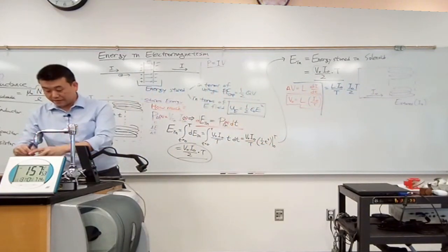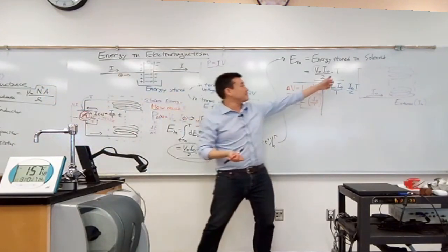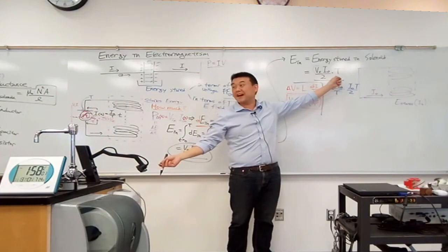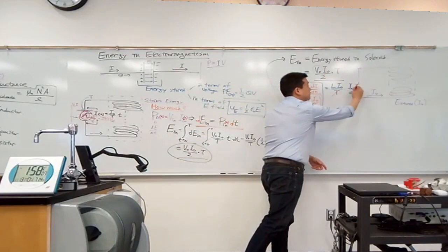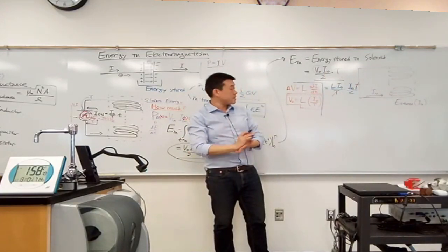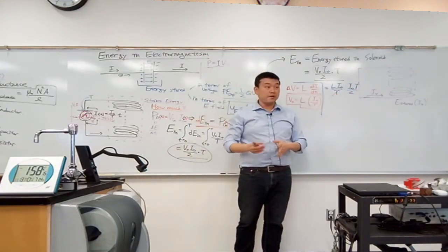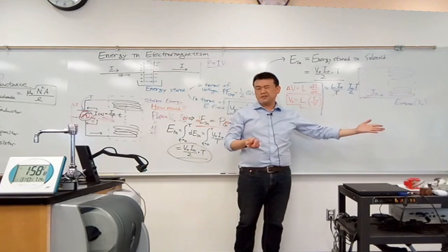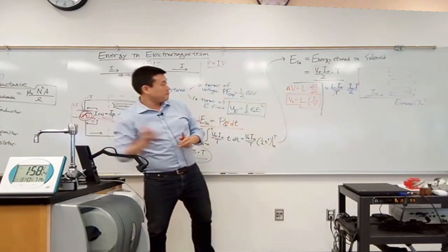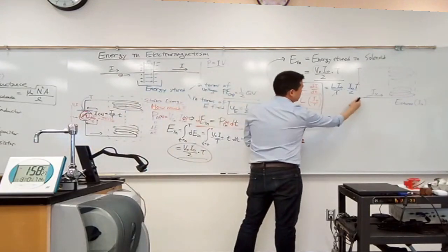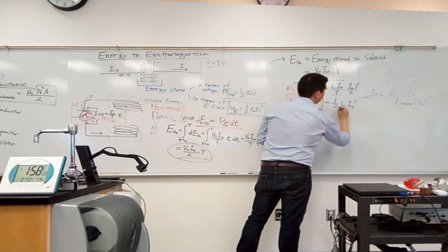That's kind of convenient. The thing that was making me hesitate a while back, if you noticed, was that I had this time T that I didn't want in my final expression either, because that's a sort of arbitrary thing. Here, you see that it cancels out. So in my final generally applicable expression, it doesn't depend on that amount of time either. It doesn't matter if it takes me a minute to charge the inductor or a year. So if I write out this expression, it becomes 1/2 L I naught squared.